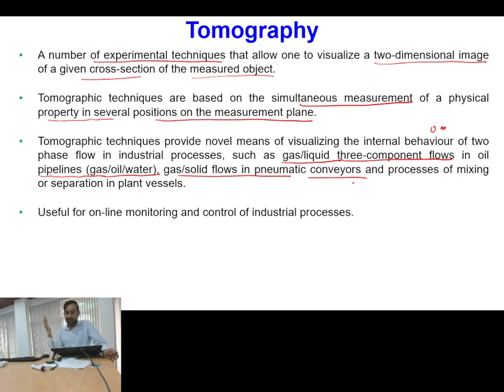So if you see, the process industry is like that, you have to go for online monitoring. Typically, once the boiler of a thermal power plant is stopped, it takes around 2 to 3 days to reach the steady state condition again. So the process is not that easy. That's why in process industry you will find very planned shutdowns. They have a special schedule that in 1 year, for 15 days or 20 days, they will go for the plant overhaul.